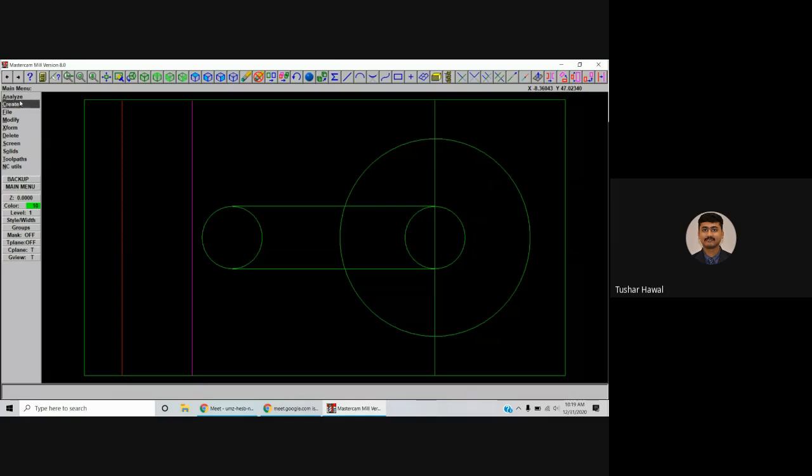And next, I am going to create a horizontal line from the center of y. So that is x value 0, comma 26.5, which is exactly at the center. Till this particular line I will create that line. Now this is the line which is actually at the center. Now this line I'm going to offset by a distance of 24 on the upper side and 24 on the lower side.